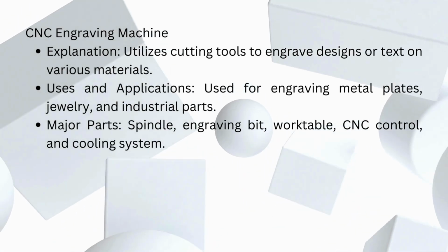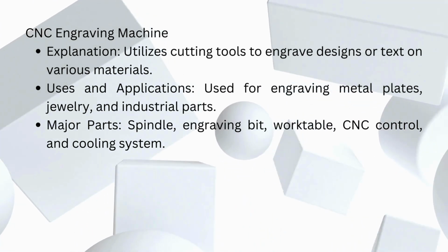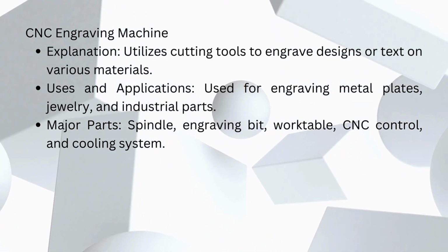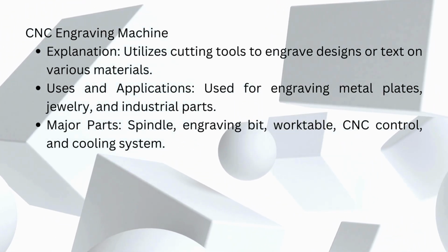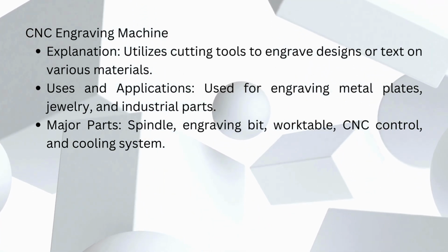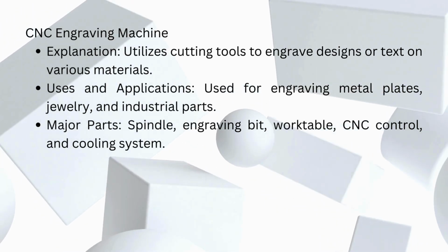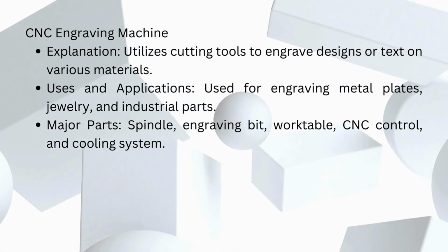CNC engraving machine. Explanation: utilizes cutting tools to engrave designs or text on various materials. Uses and applications: used for engraving metal plates, jewelry, and industrial parts. Major parts: spindle, engraving bit, work table, CNC control, and cooling system.